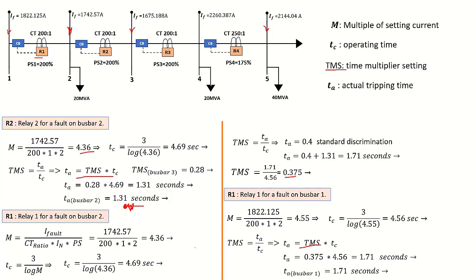Okay, and for most national electrical standards and regulations, this tripping time must be less than 2 seconds. So it cannot be over 2 seconds. That is too much time. A lot of things can already start burning. So it happens very fast. But if there is a fault somewhere along busbar 1, and it happens instantaneously, it trips the circuit. So that is how this busbar arrangement is done.